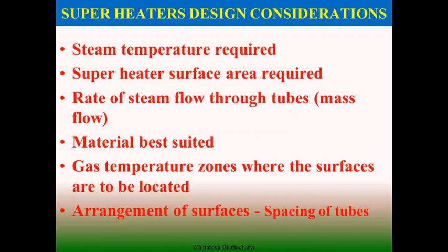As maximum heat is available within the furnace, the platen superheaters are exposed to the furnace and receive the radiant heat. In the second pass the availability of heat is less, and this is the first phase of primary superheating in LTSH, so naturally the heat added is also less.